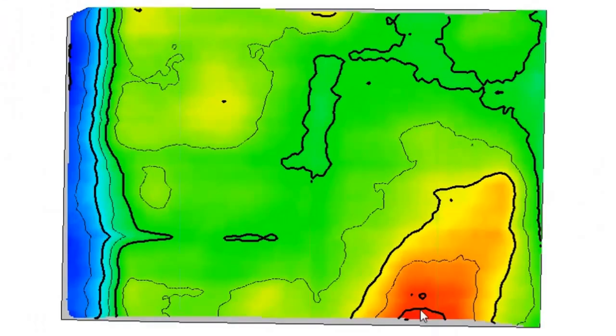elevation change. So you can see here as we drop off the top of this hill, we drop 1 foot, 2 foot, 3 foot. We only drop about 4 feet to get out to the middle of that field, kind of where that lowest lying spot is within that field. The closer together those lines are, obviously the steeper your slope.